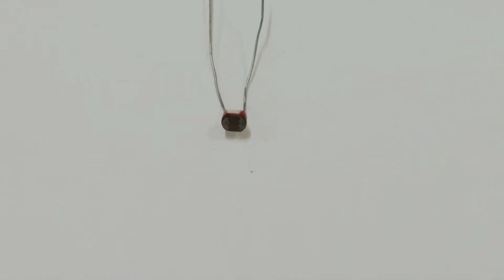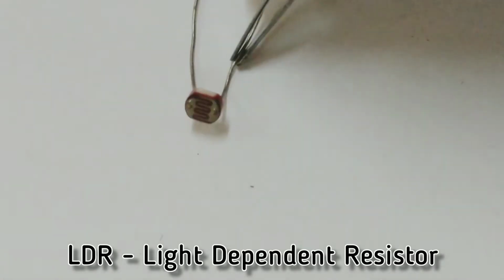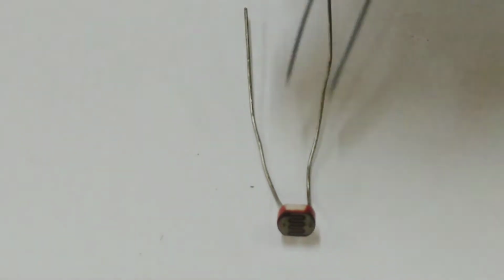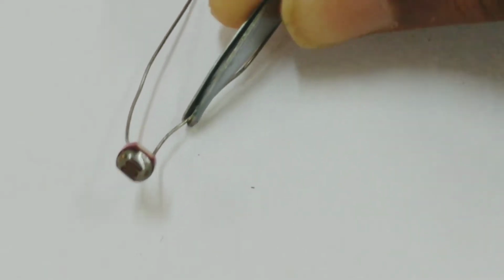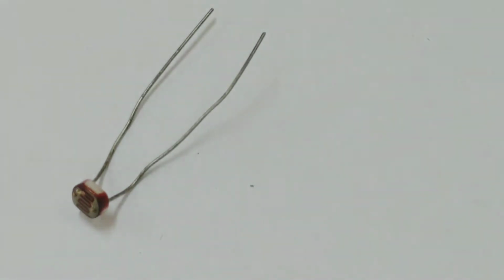Here we have a LDR, light dependent resistance. It has again two terminals, no polarities. The only difference is the resistance of this value changes according to the light that is falling on this material. As the light falls on this, the resistance value of this component keeps changing. Hence it is called the light dependent resistance.